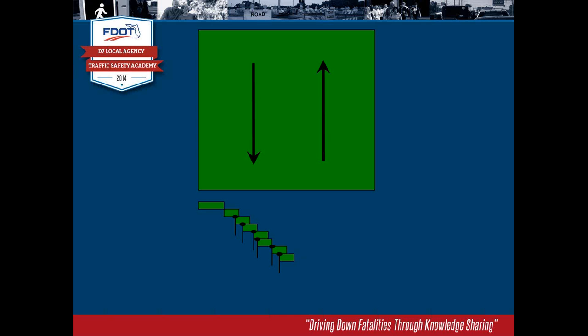And so as we keep adding these 3-second times, the amount of green time is getting stretched in those 3-second increments. Again, it's based on the value you put in for that extension. But as you keep extending, vehicles are detected as they run over the detector or are detected on video. If you reach a place where there's a greater than 3-second gap, so it counts down 3, 2, 1, and when it gets to 0, it says, okay, there's nobody else coming. I can now give green time to somebody else, and that's what's called a gap out. The signal gaps out because there is a greater than 3-second gap between vehicles being detected.